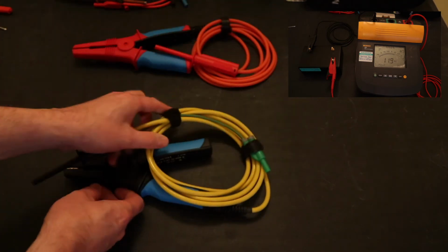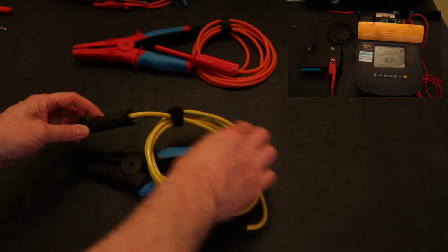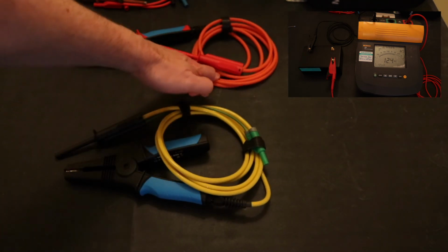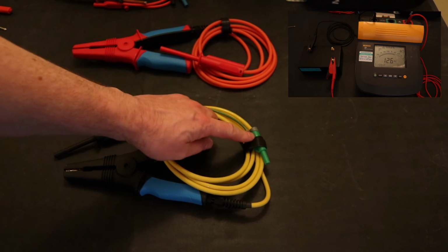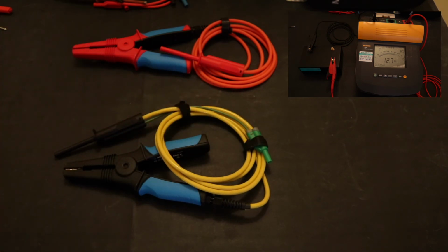Flip it over is best actually. That's this green wire here, and there's a shield running all the way up this lead, so if there's any leakage between this lead into this lead, it will hit the shield first. The shield will take it into the guard terminal of the insulation tester, and the insulation tester will ignore that leakage current and remove it from the overall reading.